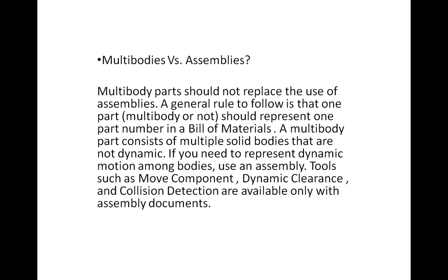of materials. A multibody part consists of multiple solid bodies that are not dynamic. In other words, they don't move relative to each other. And what you lose out on are things like move component, dynamic clearance, and collision detection if you don't use assembly documents. And that still is true today, is that you do lose out on some of these tools. But I want to show you just some tricks as it relates to bill of materials and stuff later on here.